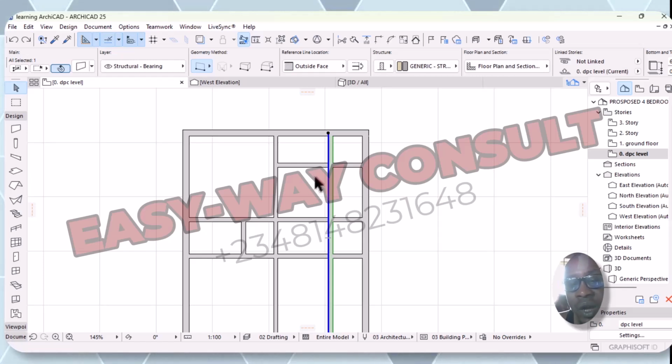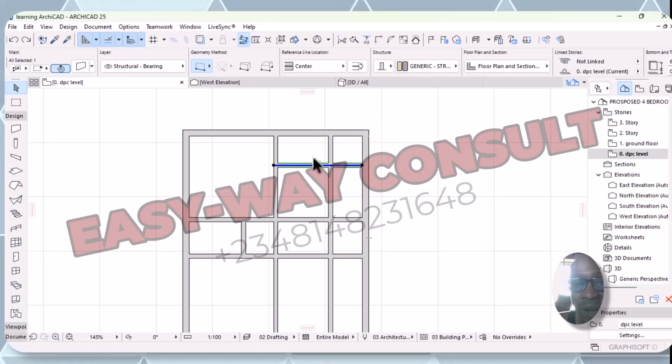These are the reason why you sometimes get it like this. If you want to measure and copy, or dimension to get exactly the measurement of the room, you have to add the size of this block to your measurement before you drag, but with this center you don't have to do that. You just click exactly what it is.